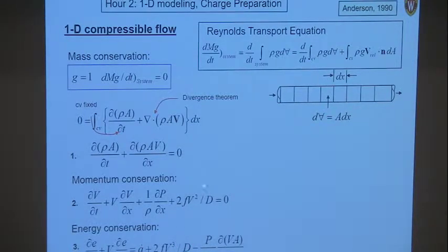And then because of friction, I actually have dissipation occurring, or heating, that contributes to the energy equation in the amount of V cubed and my friction factor. And then the final term is our pressure-volume work term. It takes some work to push the fluid across these surfaces, and that's where this term derives from.